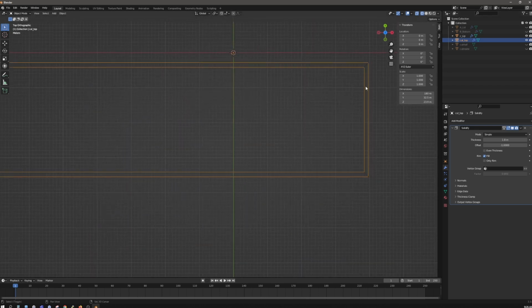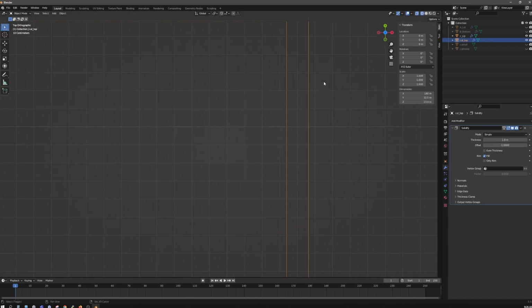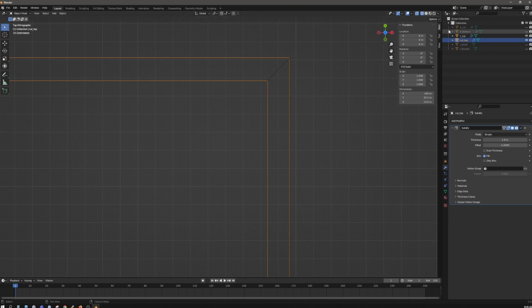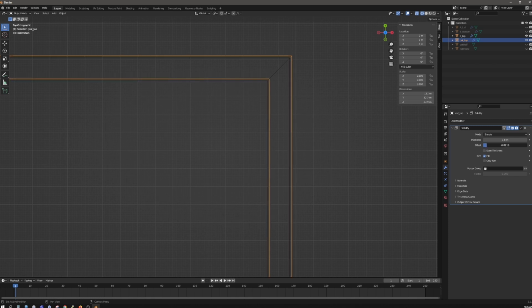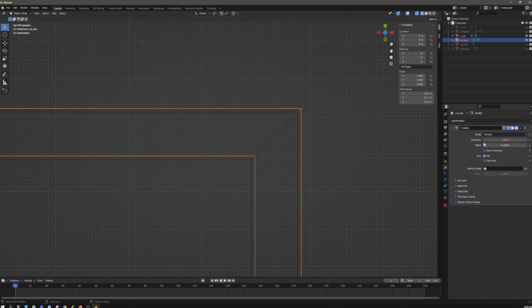Here's my top view. You've got to consider tolerance. Now, this is definitely very dependent on the 3D printer. I kind of know what mine is, so I don't really have to worry too much about it, but you do need to create a gap between your cut and your actual lip wall. So this is all for the tolerance of the 3D printer. I roughly know what mine is, so there's a little bit on the outside there, and then make this a little bit bigger.